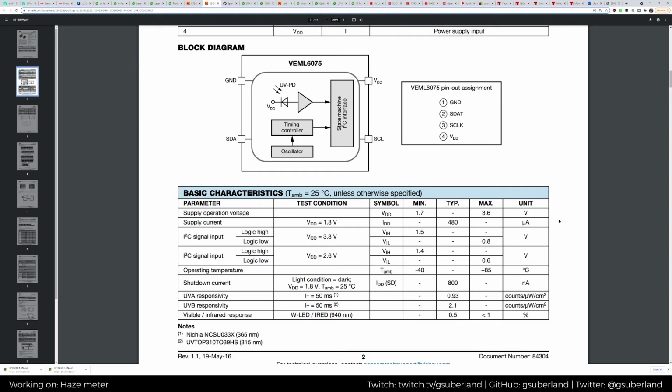It's a little bit like, you know how you get those environmental sensors that say eCO2, and it's like, oh, it's a CO2 sensor. No, it actually can't measure CO2 at all. What it does is it measures gases that also exist as combustion side products, and then calculates how much CO2 would have been produced through those combustion side products based on the concentration that it can see. Which means that if you're a human being sat in a room breathing out CO2, it detects sod all.